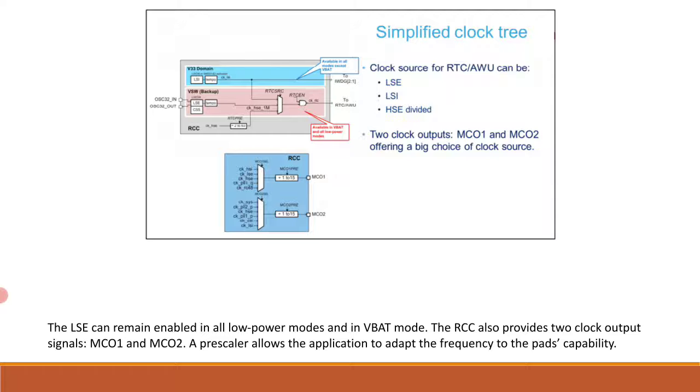The RCC also provides two clock output signals, MCO1 and MCO2. A prescaler allows the application to adapt the frequency to the pad's capability.